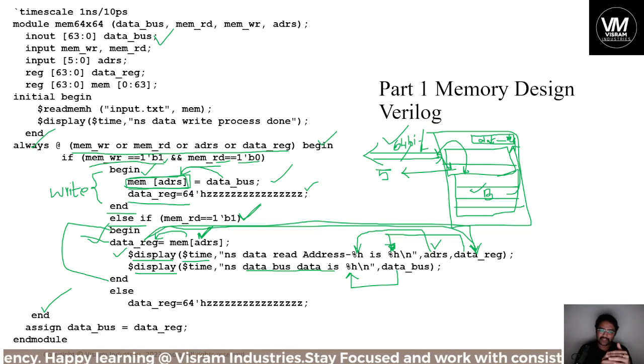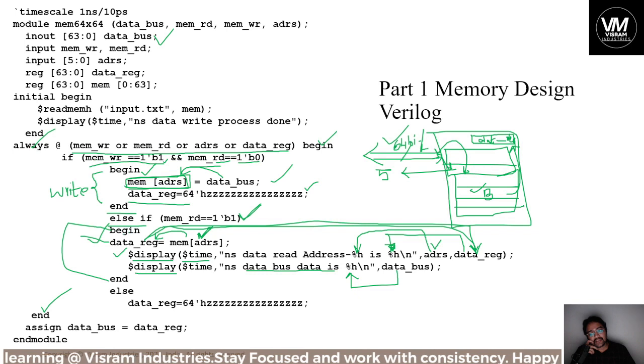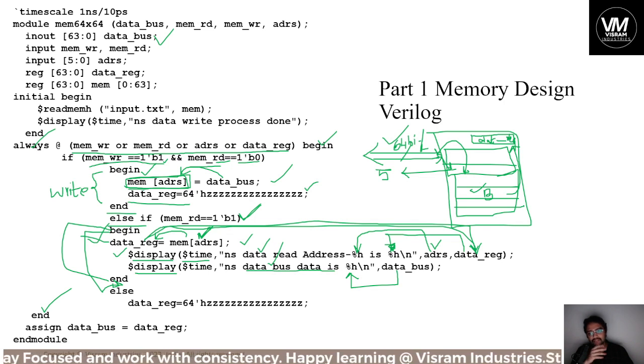If you have got confused with begin and end, when to write the end, simply, if you know that more than one statement is there, then simply write begin and end within the else if condition or if condition. There ends the matter. In the if condition, here you can see begin and end because of two statements. In the same way, in the else if condition, you can see more than one statement. Hence, you are writing begin and end.